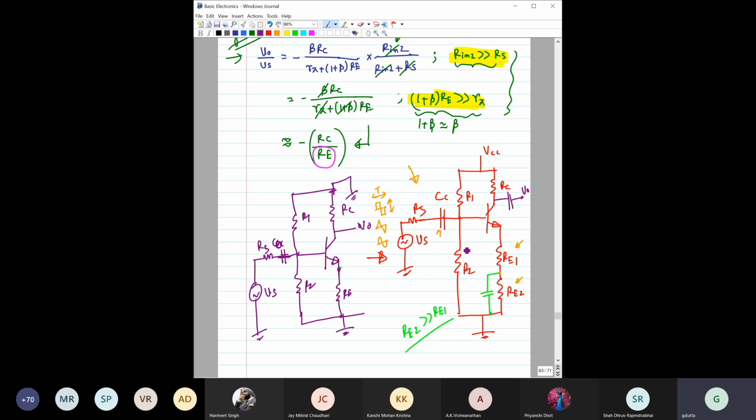In that video I will show you that first, let us fix the amplitude of the signal, and let us also fix the frequency of the signal from the function generator. Then I will show you the gain in this condition, when the capacitor is connected, and you will see a higher gain. Then we have a knob, a type of switch here. Then you open the switch, which means this capacitor is now disconnected. Then you will see that suddenly the gain has fallen.